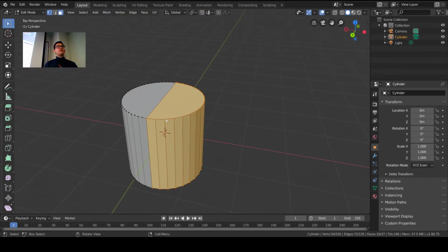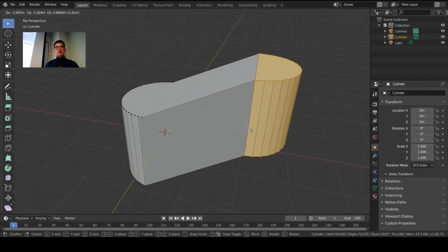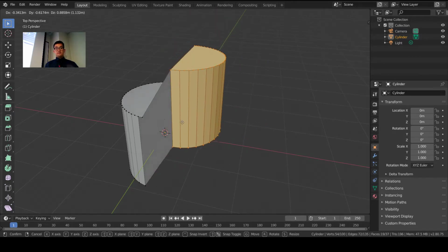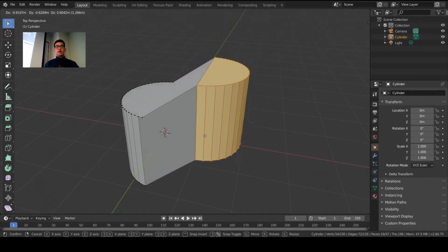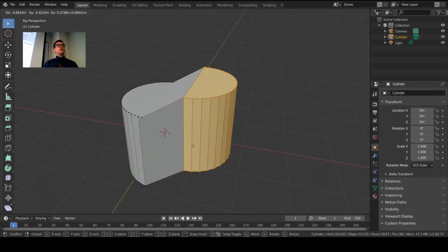And so the hotkey to move something around is G. If I press G and drag my mouse, I'll be able to change this. But I want it to be more precise. So if I wanted to translate it across the x-axis, after pressing the G key, I can press X to lock to the x-axis. And those hotkeys are all labeled down here if you ever want to look at them.